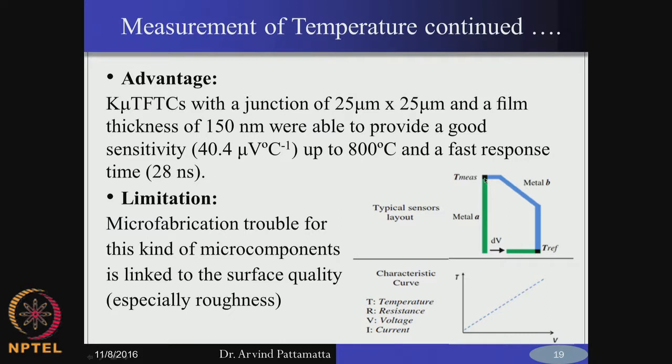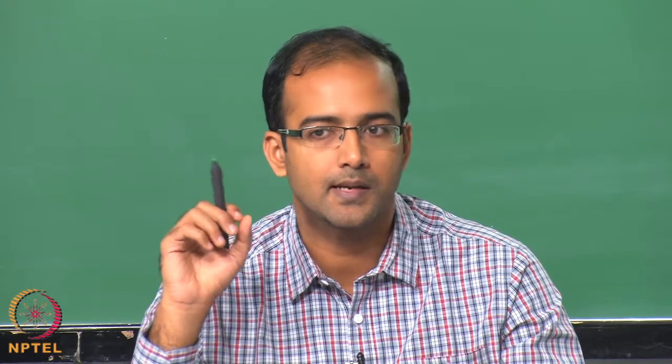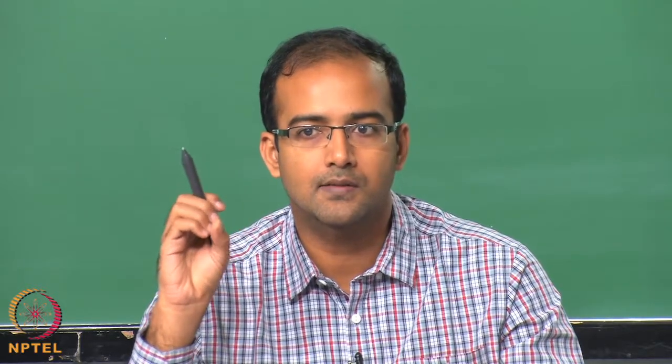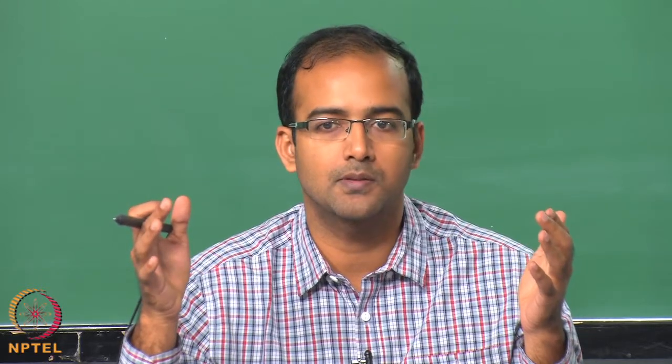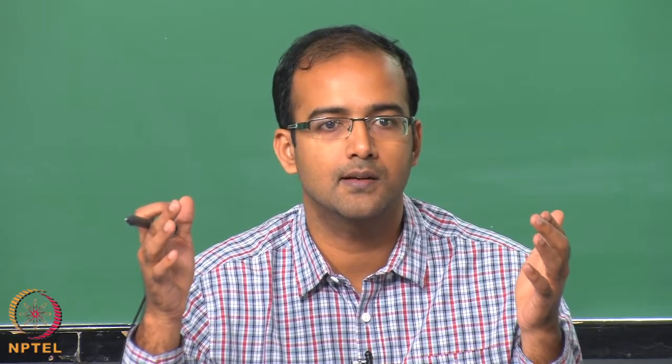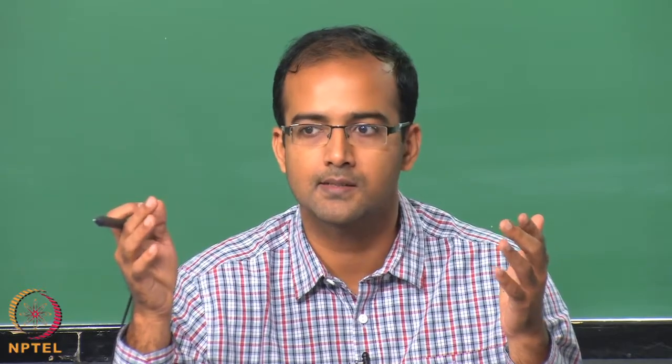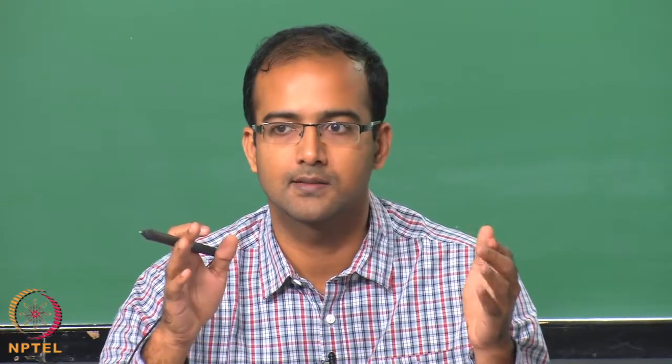Okay. And also the other important challenge with micro thermocouples is the response time. Very good sensitivity means the response time has to be very fast. It cannot be of the order of standard thermocouples. Standard thermocouples can respond within a few microseconds or milliseconds, but micro thermocouples have to respond on the order of nanoseconds.